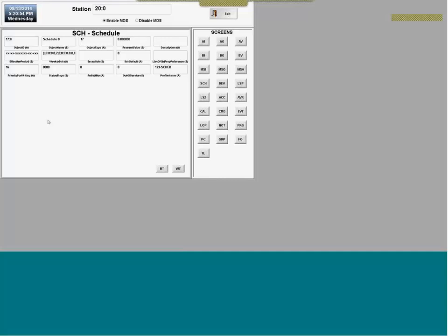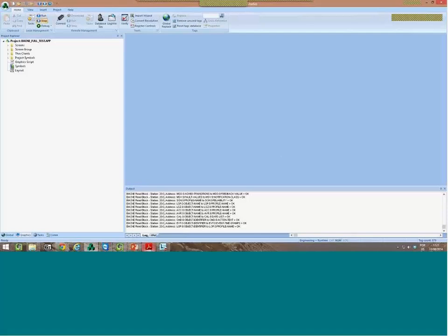Okay, so you can see that some of the properties are easy, like object type. It is an integer value. A present value can be integer, can be real, but there are some that are a little bit more complex, like, for example, effective period or weekly schedule, or the worst one, the exception schedule, right? In fact, you can see these too in the documentation. It has all the formats. For example, let me show you the schedule object.